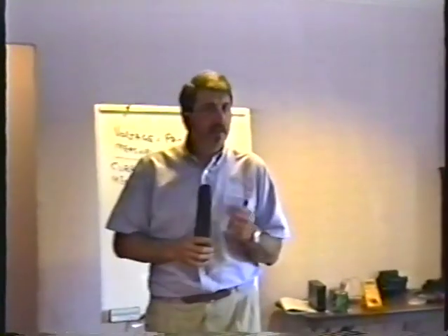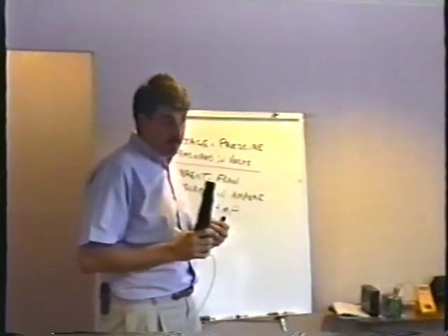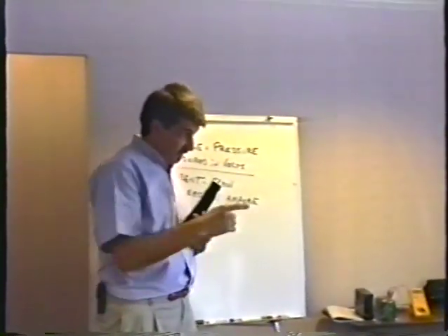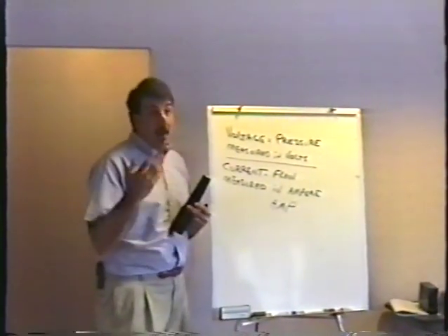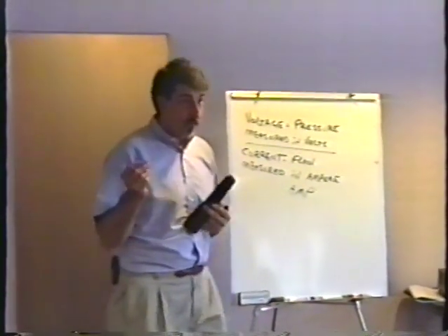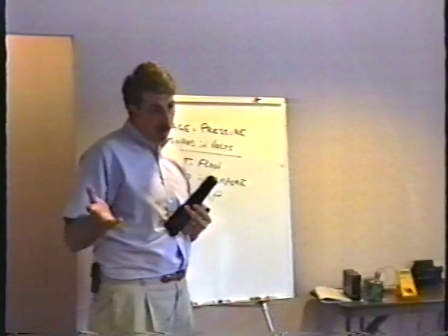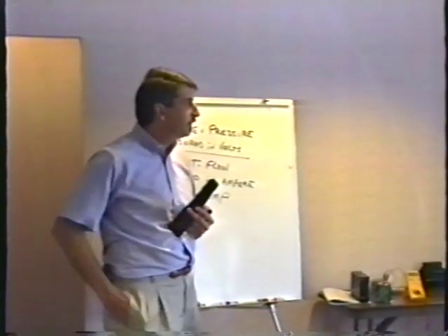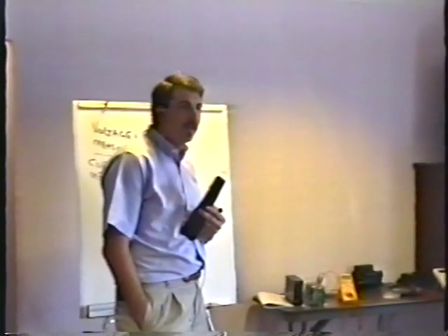And by the way, your average video game only draws about 1.5 amps to 2 amps out of the AC power receptacle. This is especially important for those of you that work in arcades or are setting up arcades. How many games can you put on one circuit breaker? Well, if you have a 20 amp breaker, obviously, if you put 10 on there, you'll be fine, 10 or less.